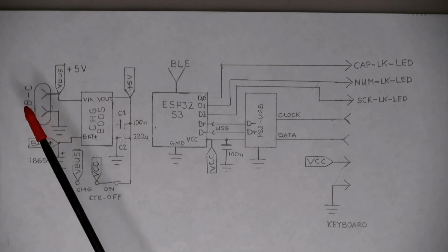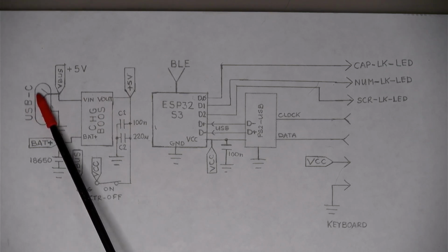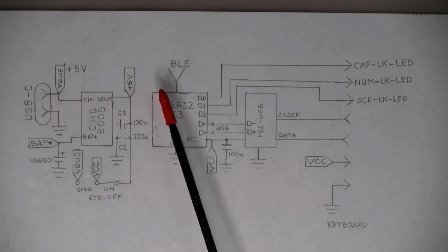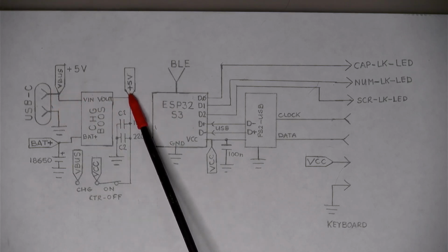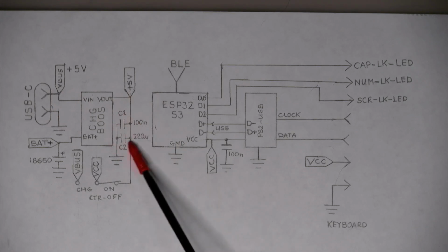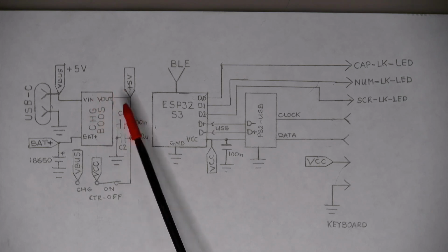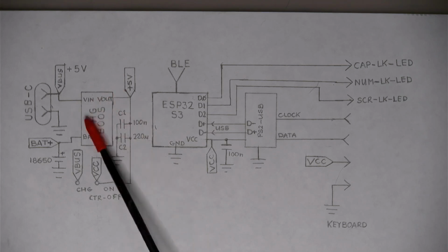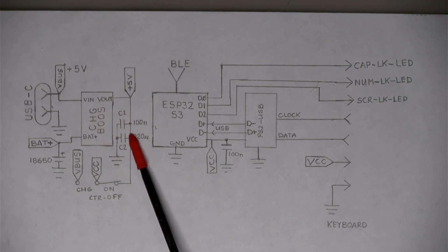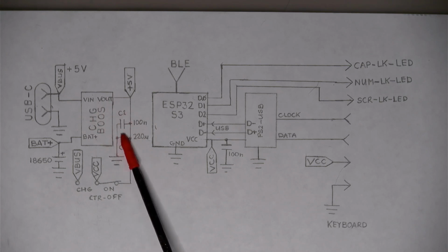Of course, it will also draw the power from the USB bus if needed. In any case, we've got the plus 5 volts output. We've got a couple of capacitors there to remove any remaining noise that the board might output, because it is, after all, a switch mode boost converter, so there's always a little noise, and I find it a good thing to put some little capacitors on the output of it to limit that.